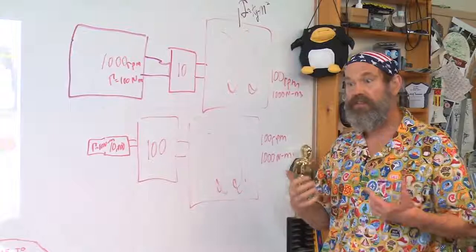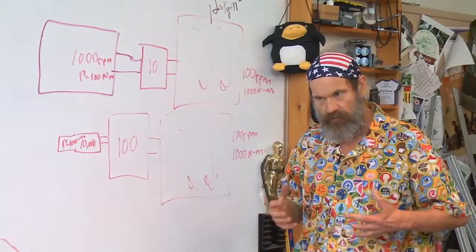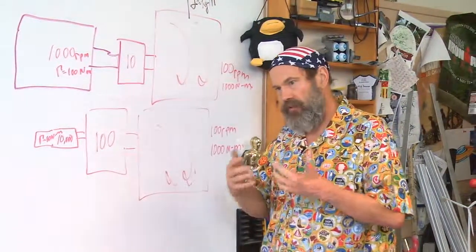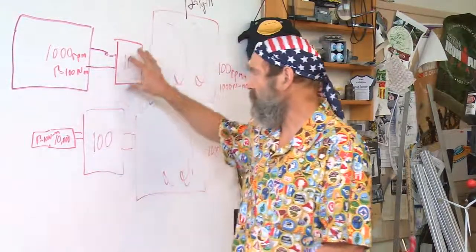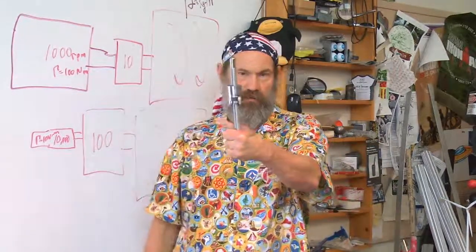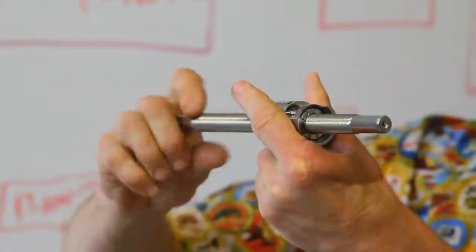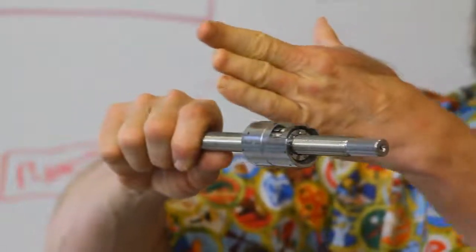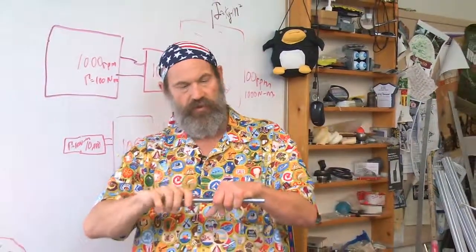So that's the logic and the rationale behind how we're going to take from the power source an appropriate transmission and get to the output load. It can be a rotary motion gearbox. The same type of analysis works for this transmission. Remember, for a screw, there is a transmission ratio of 1 rotation equals 1 lead's worth of motion in translation. So everything we talk about for rotary motion, there's an analogy for rotary to linear motion.